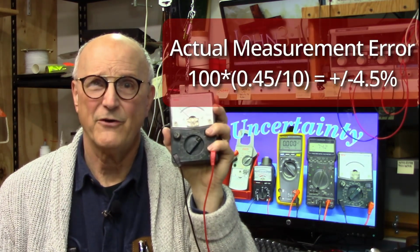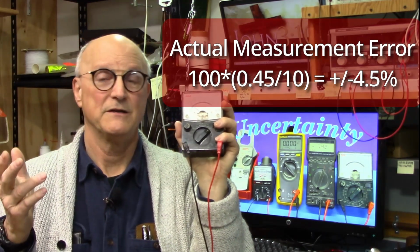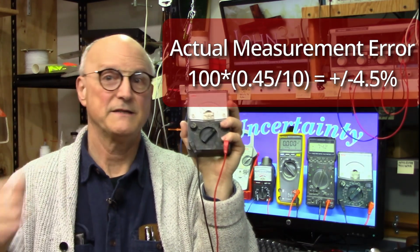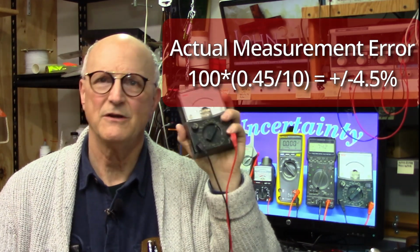The actual error in the reading itself would be 100 times 0.45 divided by 10, which is the voltage that we're actually reading, is equal to plus or minus 4.5% when measuring a 10-volt signal on a 15-volt scale.